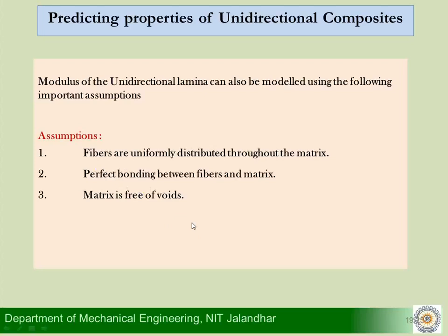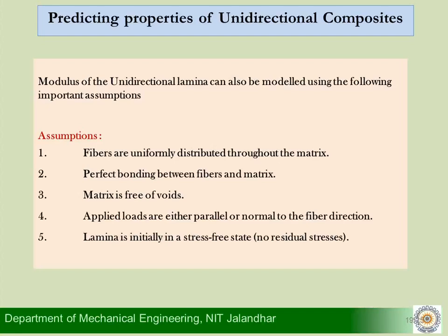That's another assumption we have here. The next assumption is that we'll be analyzing loads, to begin with, only in directions which are either parallel or normal to the fiber direction. So you may be talking about loading along the L direction or loading along the T direction. And initially the lamina is in a stress-free state.